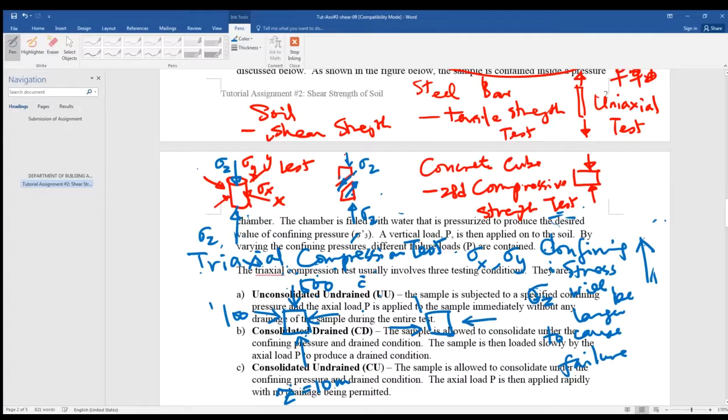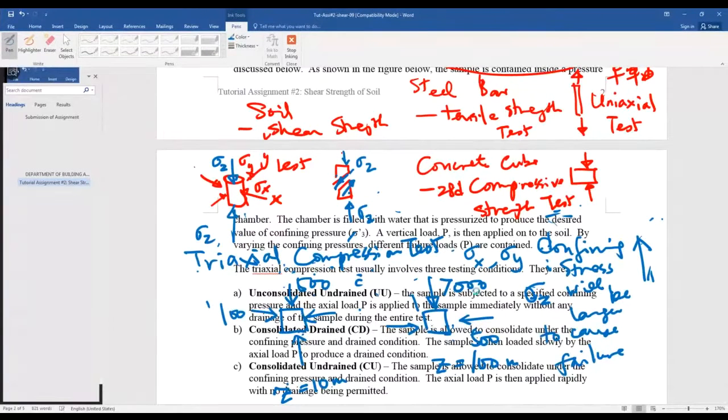you have the confining stress much greater, right? Say that's 500. So what would you expect the vertical stress there to fail this soil at Z, say 100 meters below ground surface? Now we believe that it could be 7,000. In other words, at a greater depth, the soil could only fail at a vertical load of 7,000 kPa.